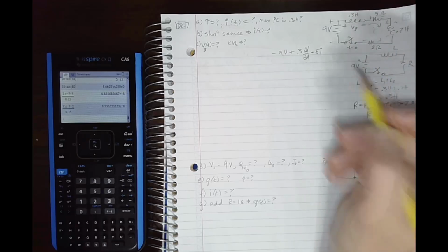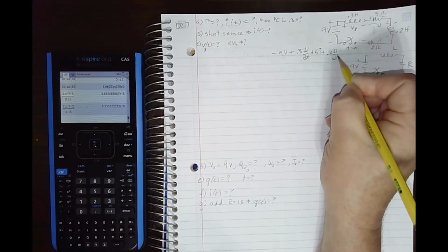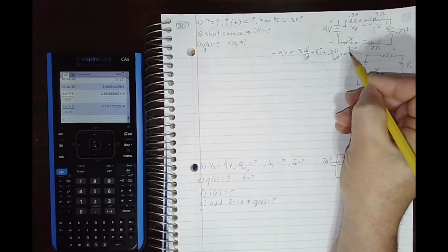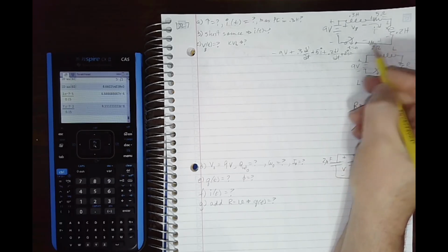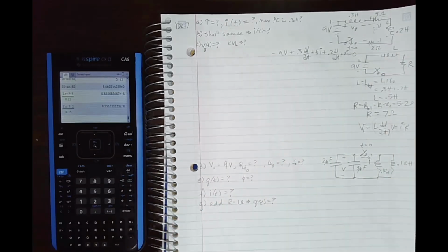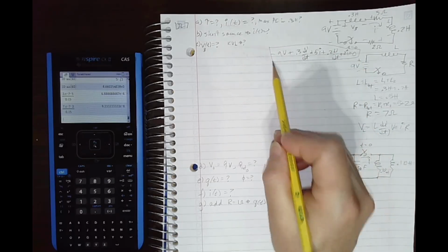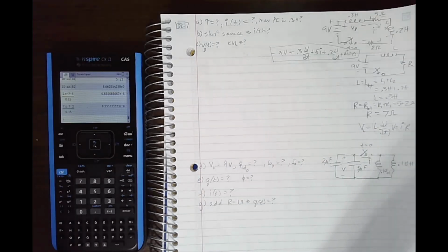Hit the second inductor, it's another, plus 0.2 di/dt. Then hit the second resistor, plus 2I. We came all the way around back to where we started, so it equals 0. So for the whole circuit, we have this kind of differential equation, and as you might guess, people have gone through and solved this differential equation many times.